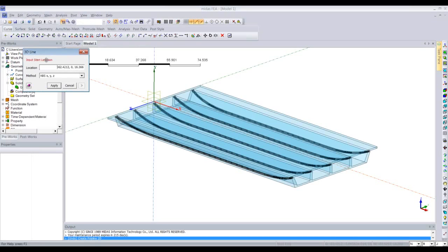So basically, the idea behind creating the tendon is to have a curve. And once you create the curve, you will mesh it, and then it will be categorized as a tendon. So the tendon definition tool that we used was only to create a curve. So right now I'm creating one more curve here. So I'm putting in the global coordinates.